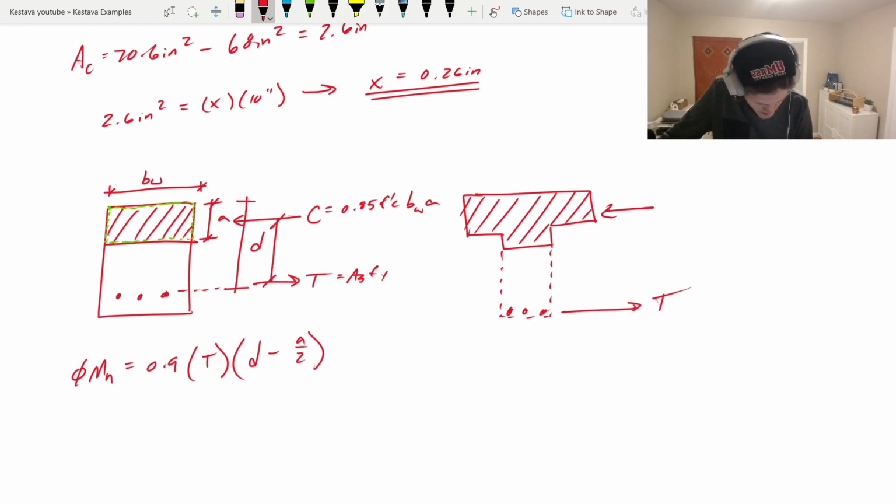But you have C up here, but where does that compressive force live? Where is it in here? Is it up here? Is it down here in green? Is it black? Is it right here? We don't know where it is, but we need to find that. Ultimately, we need to find this distance, this moment arm. In order to find that, we go way back to the basics. We have a geometry, and we need to find the neutral axis of that shape.